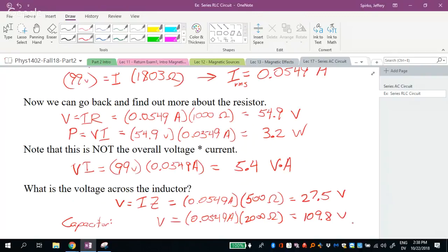And it's because the capacitor doesn't generate voltage by receiving voltage. The capacitor generates voltage from having charge accumulate in the capacitor. And it was actually the inductor in the circuit that was getting some current flowing and then pushing extra current into the capacitor so the capacitor could generate this extra voltage.